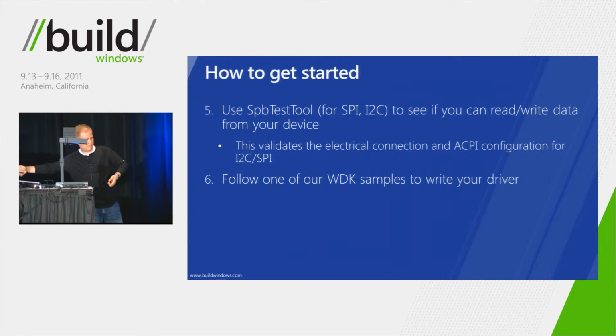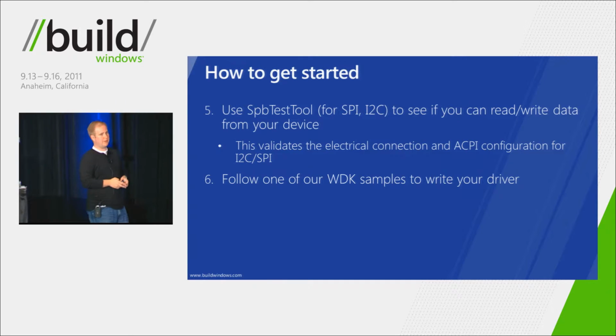Over here again, use the SPB test tool, which again, we provided in source. And what you do is you load that little fake peripheral driver up, make sure your ACPI looks good. You poke and prod at your device digitally, maybe write a few bytes, read a few bytes, check to make sure the interrupt is there. That way you know everything is wired up and good to go.